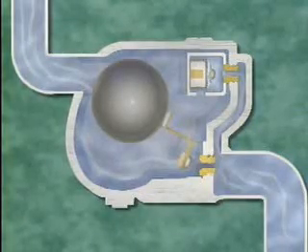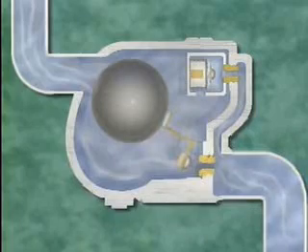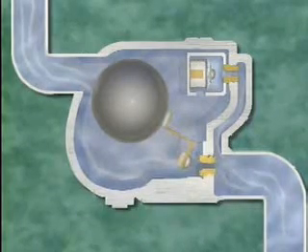If operating conditions cause condensate to build up to the point that the trap becomes waterlogged, the relatively cool condensate causes the bellows to contract, which opens the vent valve. Then the condensate drains through the open vent to the trap's discharge line.